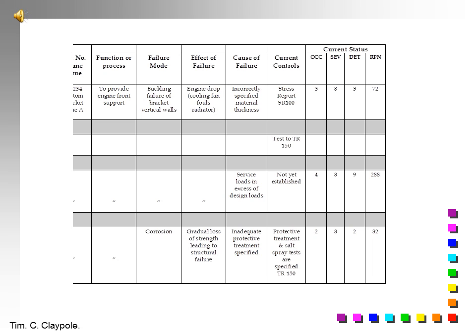The occurrence of this likelihood is 2. Severity is still the same. The chance of us getting this wrong is also 2. So the risk priority number of this is 32. So if we were looking at this design, the area that we need to pay immediate attention to is finding out what the service loads are likely to be on this component.